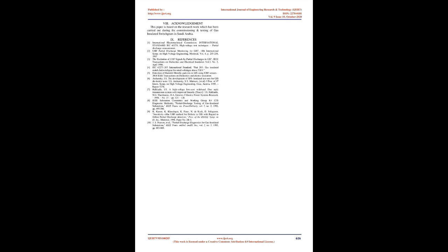B. Server. The server controls the monitoring system displays and stores the system data. It links to the PCU via serial cable for accurate phase timing from the VT inputs and alarm data. Data from the OCU is phase resolved in software and displayed in correct phase and timing. This data is then collected during operation and stored as historical information from the system. It also contains a dual LAN interface: LAN1 for the PCU local network to the OCU, and LAN2 used for remote access to the headquarters PC system.